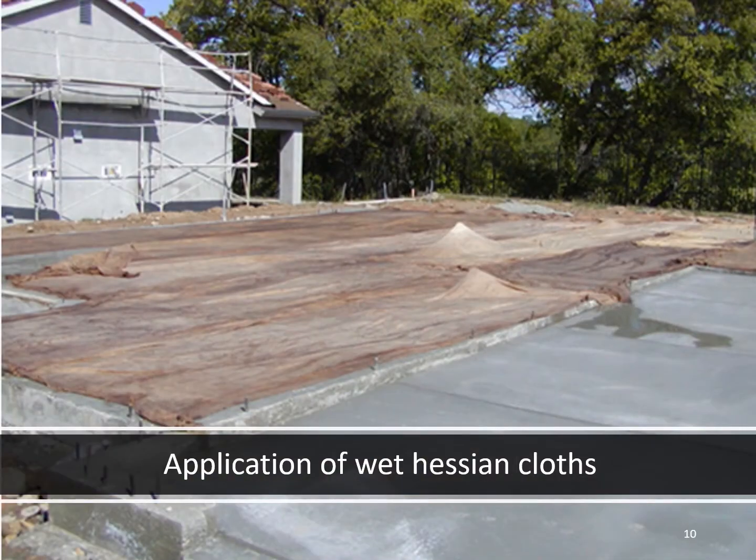Then coming to the application of wet Hessian clothes, the idea is to cover the entire surface with the Hessian clothes and then apply water through sprinkling or ponding, so that the Hessian cloth which is being spread across is completely wet, and the loss of moisture can be minimized, because this condition can be retained even if the atmospheric temperature is high. These conditions can be retained for a longer duration of time rather than sprinkling the water directly on top of the concrete.